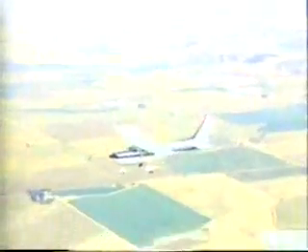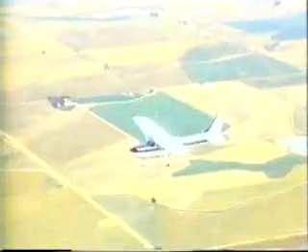During a power-off glide, the distance traveled is the same regardless of weight, provided the LD max angle of attack is sustained. Since most light airplanes do not have angle of attack indicators, manufacturers list the best glide speed which corresponds to this angle of attack. Often, only one speed is listed in the POH, since the range of possible weights is rather narrow.